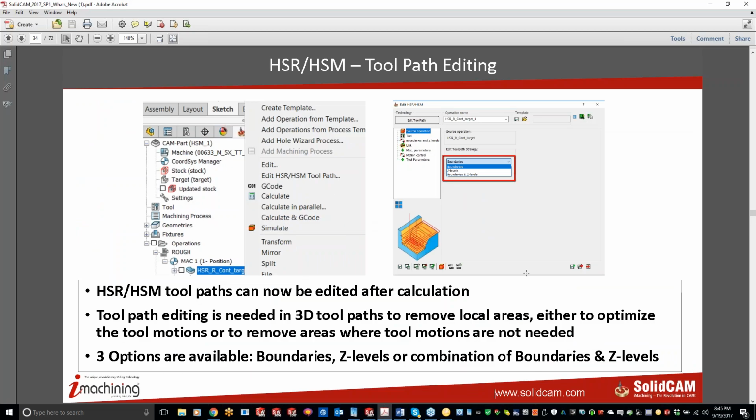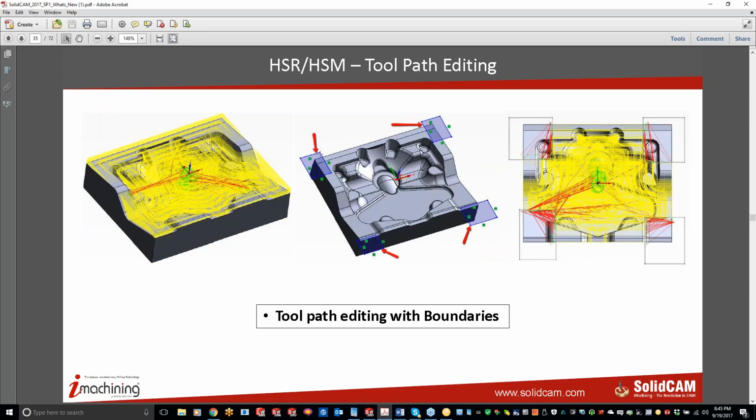So let's say we have 4 corners that we don't want to touch. You'll see over here on the left-hand side, we have toolpath coming all around there, but if we had toe clamps on there, we would completely avoid those. Now you will see some red lines coming across that, but remember that is up at your clearance plane. If we had a toe clamp in there, we can increase that clearance plane higher or lower to accommodate those. But this is a completely new and nice feature that they added in there.